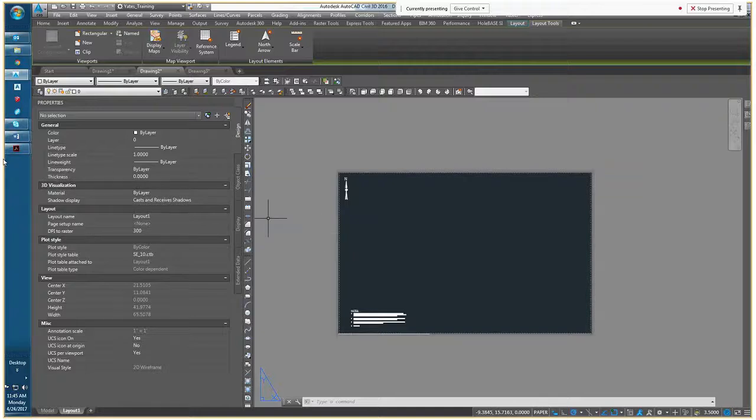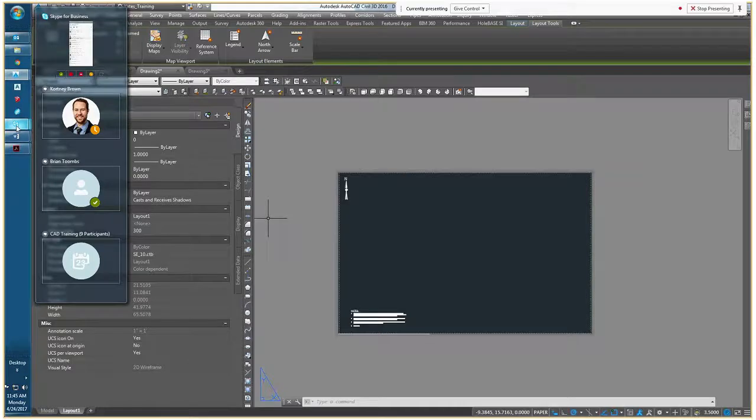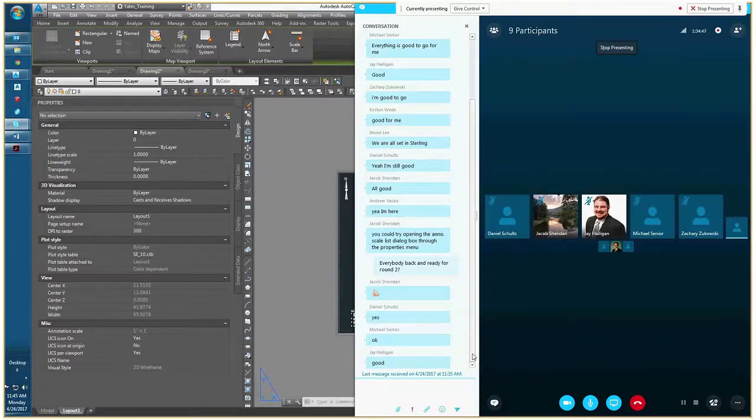This is probably one of the most important things that we can have everybody understand today, is that we have two different templates for a reason, and it's really, really important that you start off with the right template. And if you find that you're working on a project where people are using the Civil 3D template and they should have used the detailed DWG template, it's really easy to copy and paste those to original coordinates to get that into the correct environment that it should be.